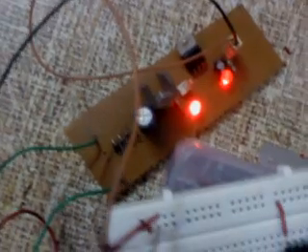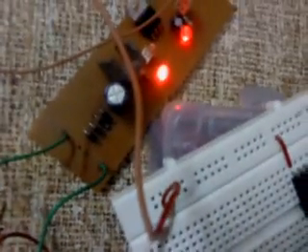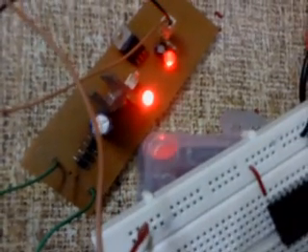For the TTL logics, I only required the 5 volt for the microcontroller and all these LCD displays. The current requirement is higher, but in this circuit only a few milliamperes are required, so this is sufficient here. This is the transformer which steps down the AC, and then this is the full wave bridge rectifier, and this capacitor, and this 7812 and 7805.